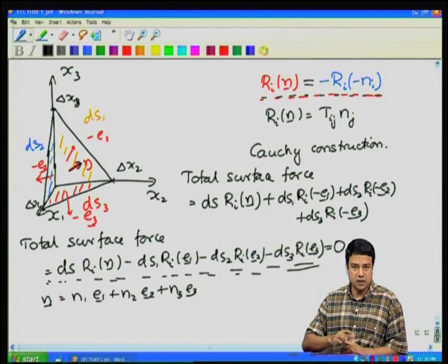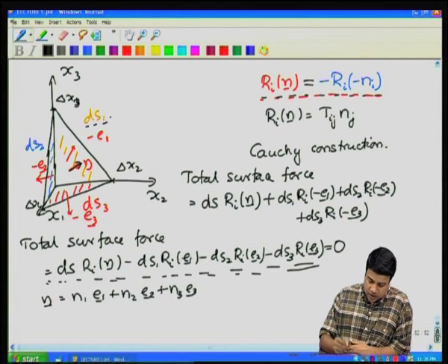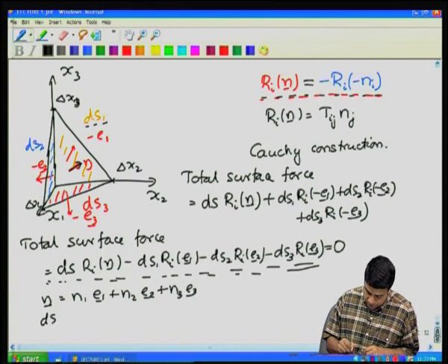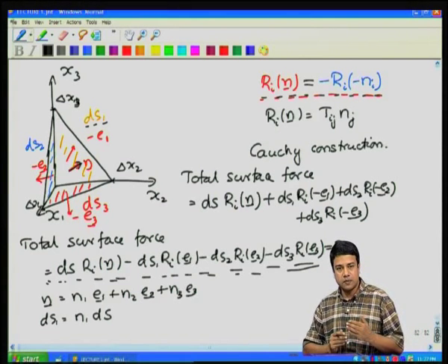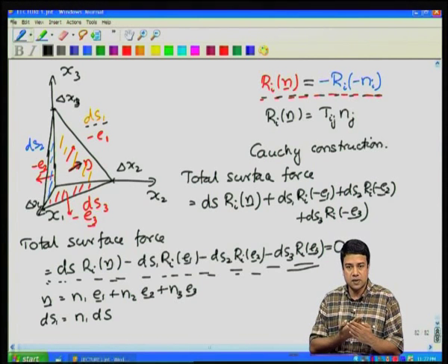Now, this surface area perpendicular to E1, the surface on the x2 x3 plane, that is this surface with unit normal in the E1 direction, ds1, it is perpendicular to the E1 plane. Okay. So, therefore, since the angle between n vector and E1 is the same as the angle between ds and ds1, I can write ds1 is equal to n1 ds. ds1 is in the x2 x3 plane, ds is the actual slanted surface.